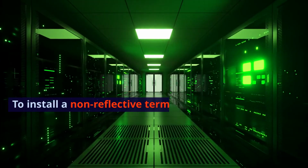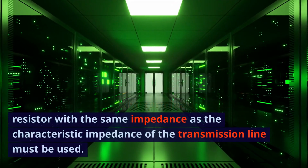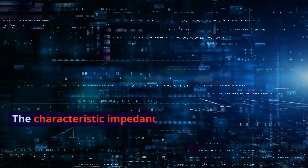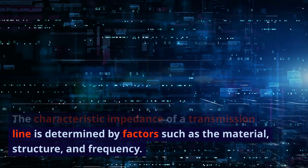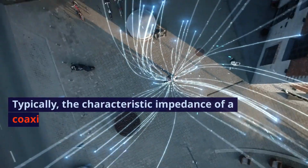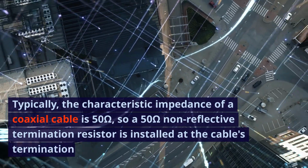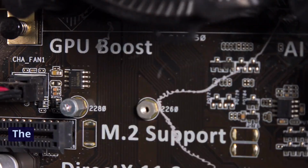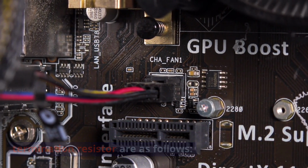To install a non-reflective termination resistor, a resistor with the same impedance as the characteristic impedance of the transmission line must be used. The characteristic impedance of a transmission line is determined by factors such as the material, structure, and frequency. Typically, the characteristic impedance of a coaxial cable is 50 ohms, so a 50 ohms non-reflective termination resistor is installed at the cable's termination. The characteristics of a non-reflective termination resistor are as follows.